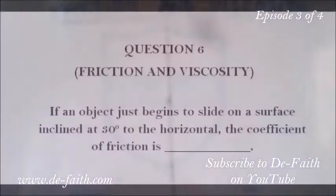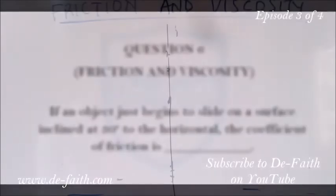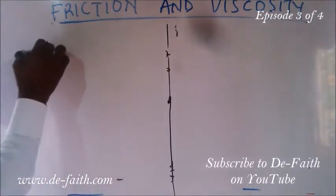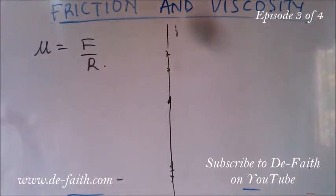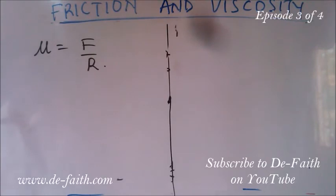Here's another question. If an object just begins to slide on a surface inclined at 30 degrees to the horizontal, the coefficient of friction is dash. The body just starts to slide, meaning that the coefficient of static friction equal to F over R. It has just started sliding, so this is the formula we apply. But we are not given any information such as F, the static friction force. We are not given the normal reaction.